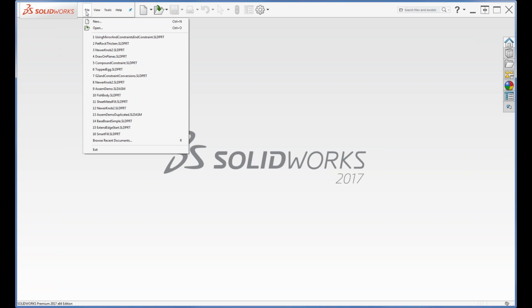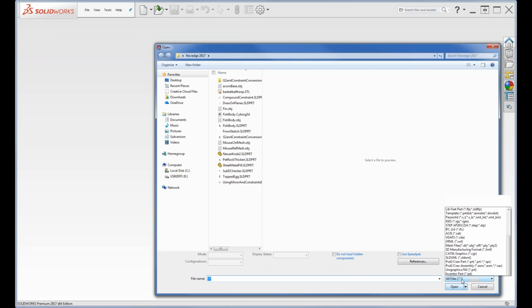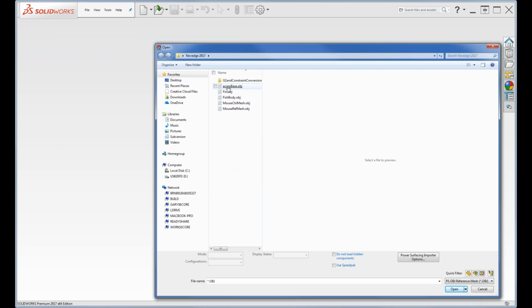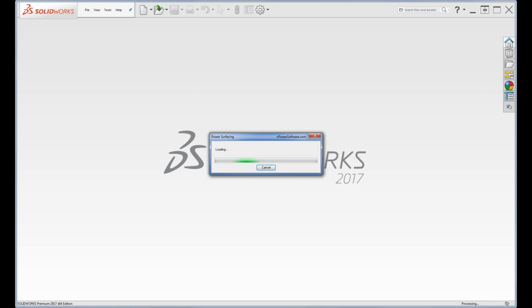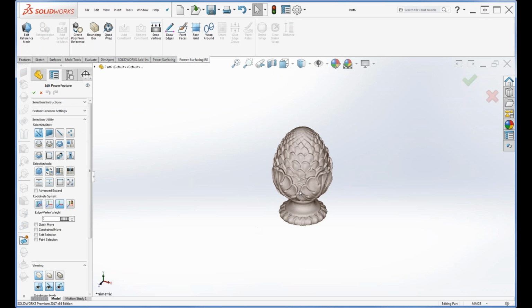And now we're going to get over to the RE side, and we've got some really cool stuff there. And for that one, let's see, this is an OBJ. So I'm going to open it up, and I'm going to pull in my reference mesh. It's an OBJ, so I want to bring it in as an OBJ reference mesh. And that would be Acorn Base. And this is a sort of a messy scan. Some of it's okay, but some of it isn't, which is going to give us a lot of other stuff we can do. Tell it what the units were on it.